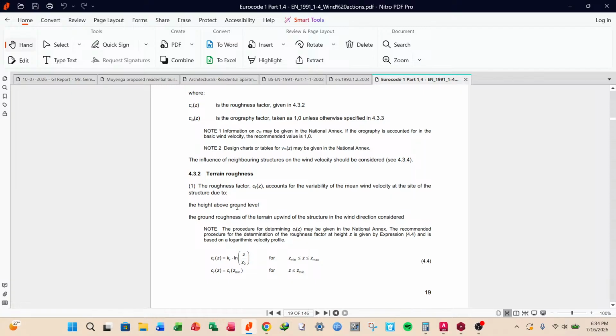But these slabs are not stiff out of plane. In the vertical direction, they are not stiff. So they transfer the loads to the stiffer members, for instance shear walls. In the vertical direction, the shear walls are stiffer. So these slabs will transfer these wind loads to the shear walls, which in turn transfer them to the foundations.